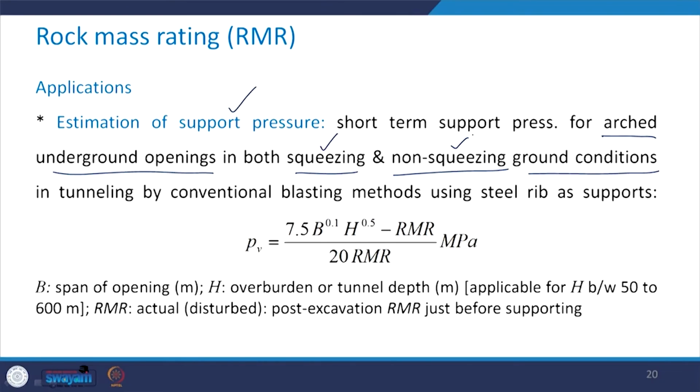For the time being, you just think about this situation, that RMR can also be used to estimate the support pressure for tunnels. So if there is squeezing and non-squeezing ground condition in tunneling, and the conventional blasting methods are used and steel ribs are used as the support, then this expression gives you the idea about the estimation of the support pressure. Here you can see that the RMR comes into picture,